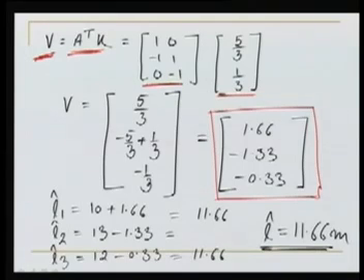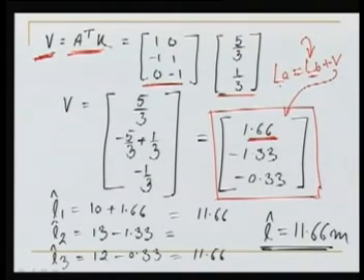Now what these V's are? What was our basic model? L A is L B plus V. Means we have determined the V. If we add these V to observations L B, we will find L A's, means L hats.